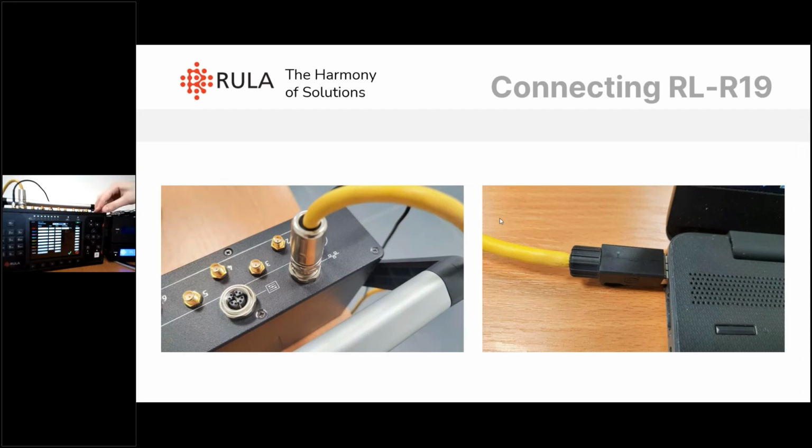I'm not sure if you will see it, but here we have the channel setup. So in our case, we're using IEEE, units are G, and sensitivity is 10 millivolts per G. Once we are satisfied with it, we press on the back, measurements, and in here we have a window that allows us to preview the input. So pretest, for example, but this is not the recording yet. So let's stop it and press the recording button.